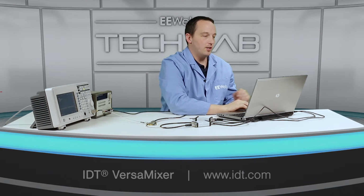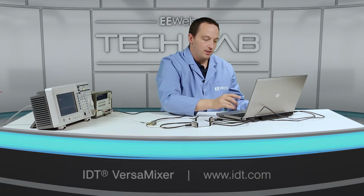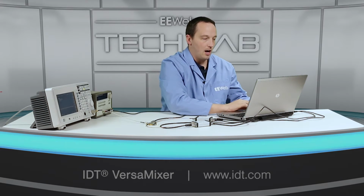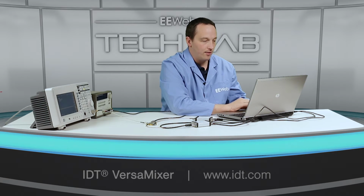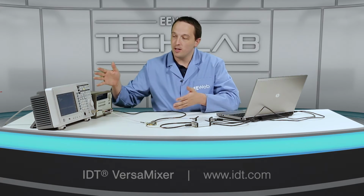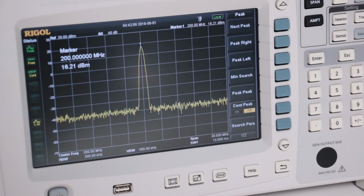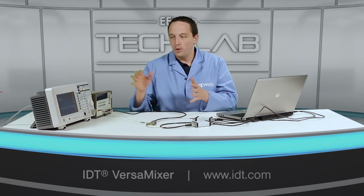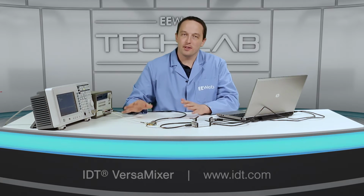Now I can go ahead and change the outputs to 3600 megahertz to kind of go to the opposite end of their range, 3800 megahertz on the RF. Turn those back on. And of course we don't change the spectrum analyzer because we're still at 200 megahertz. And you see that our signal has dropped just slightly, but to cover that range with a pretty flat gain across the entire spectrum, and we didn't change anything on the BOM. That's one of the really impressive things about the Versa Mixer.